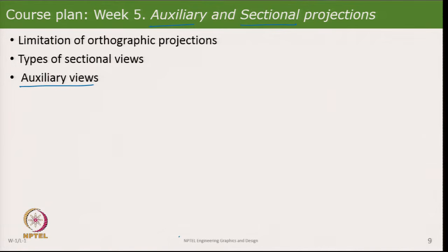And then it could have internal features, which just by looking at the object will not tell us what is inside it. That takes us into the realm of a sectional view. That means you are hypothetically cutting that object and asking, what do I see? And in many cases, when you cut that way, you see a lot more things in it.